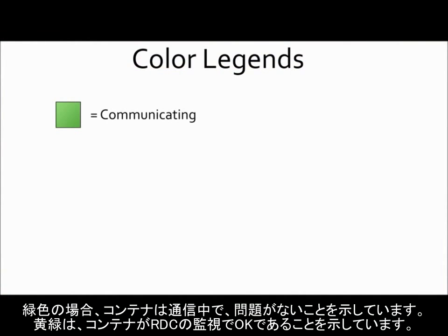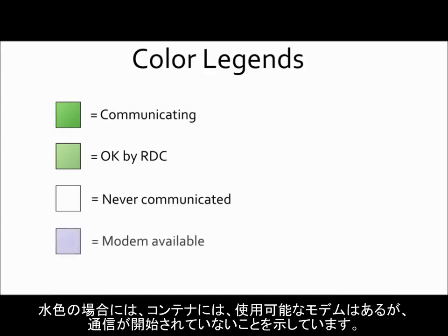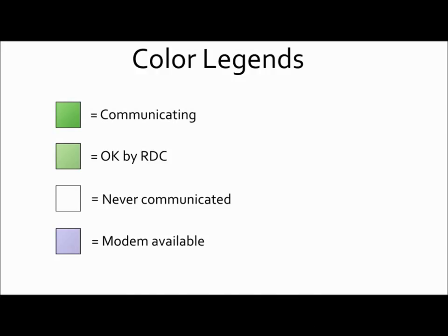If the legend is green, the container is communicating and has no alarm. Light green means that the container is monitored OK by the RDC. White means that the container has never communicated, probably because there is no modem installed in this container. When the color is light blue, the container has a modem available, but has not started communicating. If this persists, we recommend that you repair the modem.